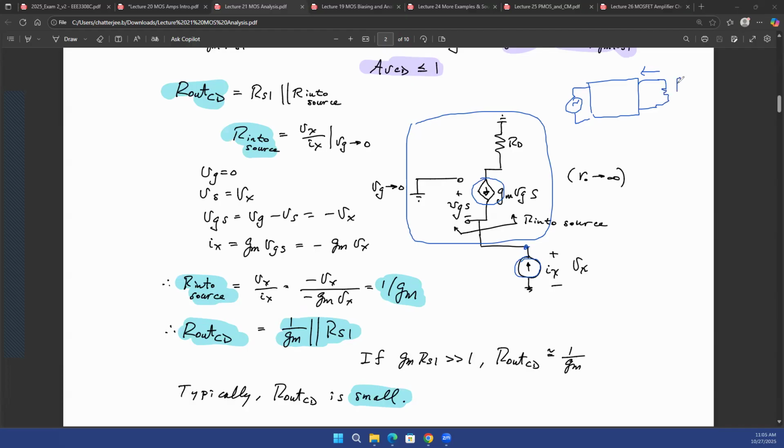This is something that we learned in the first few lectures of this course, and again in 3111. So what is the first thing you do if you are trying to find the resistance looking into this black box? Disconnect the load. You get rid of the load and you short the input voltage source.